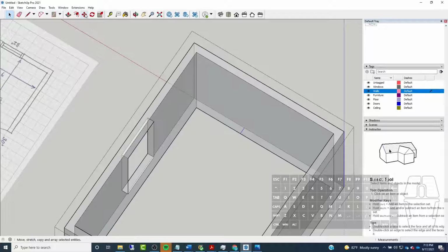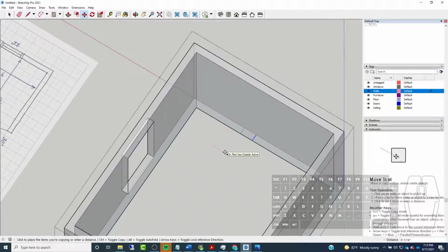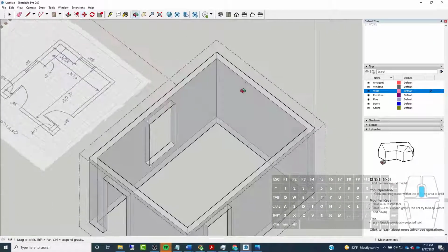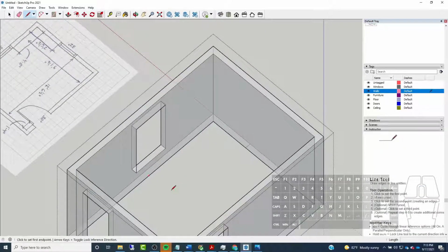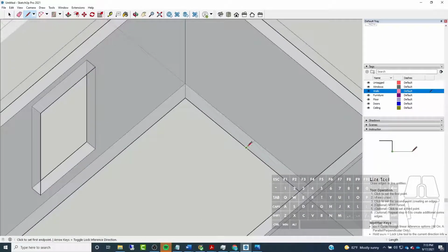Copy this line to the right, 32 inches. And then what I can do, and this is where after you do it once, it gets a lot easier. So I don't have to put in all my dimensions anymore for my windows, since I know they're the exact same size. All I have to do is start my line at my reference point here, start dragging straight up, and then hold my shift key and reference the lines over here, right?